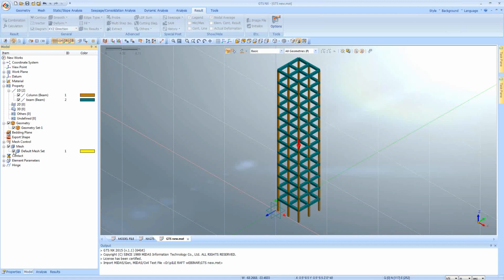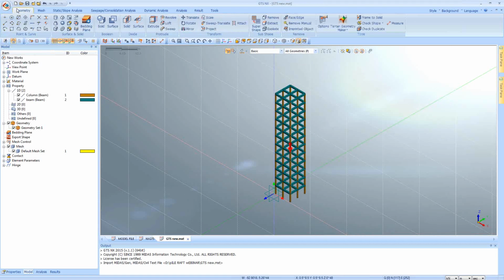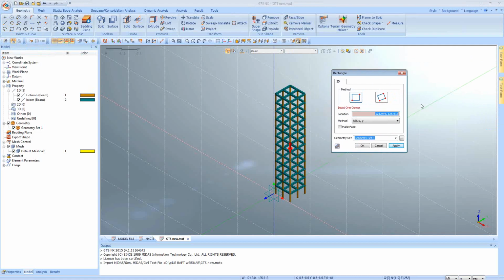Now what we need to do is create a continuum model, that is a solid model. Okay, so let us create. First of all, just understand the workflow. Whenever you start, first of all think of a 2D simulation of your 3D model, then extrude that into a 3D model. Okay, and then you can move on to the meshing and boundary part. So first of all we need to create the rectangle, which will be basically the raft. Initially I will create the rectangle for raft.